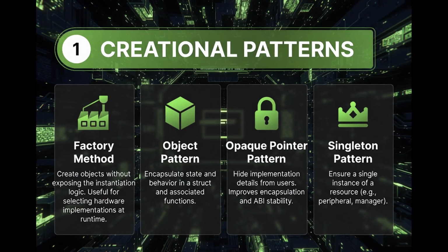Because hardware resources are unique, firmware often uses globally accessible singleton structures. However, embedded engineers use this carefully because excessive global state harms testability, creates race conditions, and complicates concurrency.